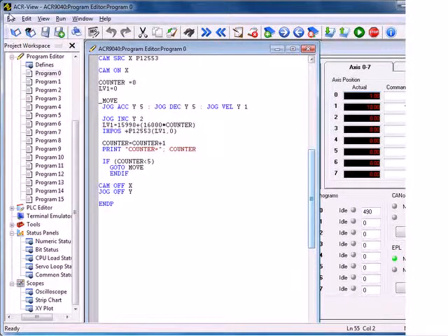Instead of moving back and forth, this axis will always move forward. I've created a local variable LV1 that increments the IH pause value. If this IH pause value wasn't incremented, it would only execute once, as the position would always be greater than 15,990 after the first move. Thus, counter would increment without waiting for the next move.